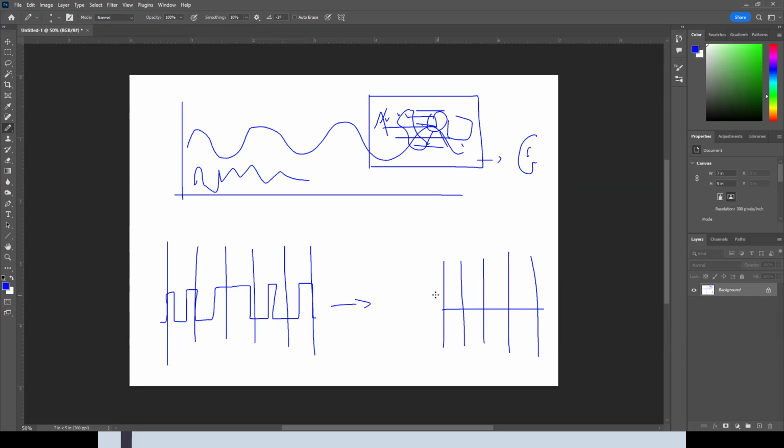The receiver is going to listen at the same speed that the signal is being transmitted. And it's going to find where the ones were, where the zeros were, and so on based on that. And if things are synchronized in a way that the listener is listening at the same baud rate, at the same rate as the signal is being transmitted, then the ones and zeros can be received properly and the signal can be reproduced on the other side.